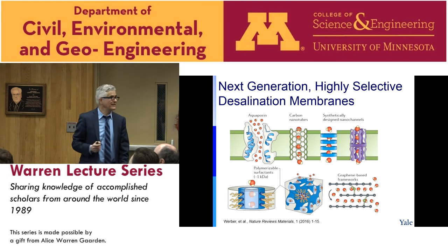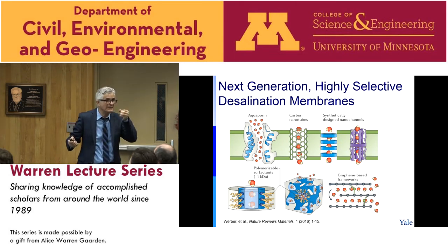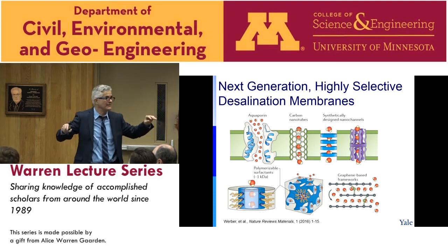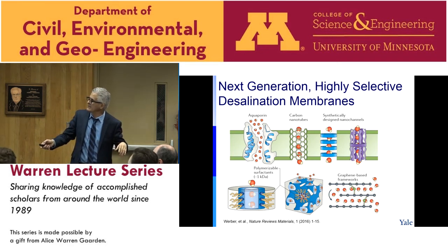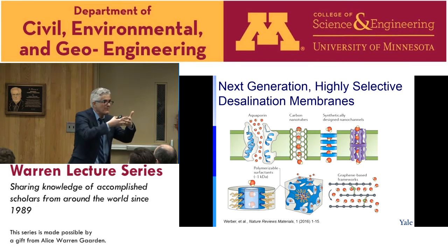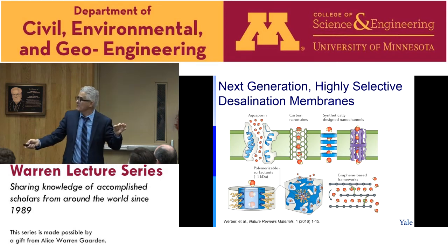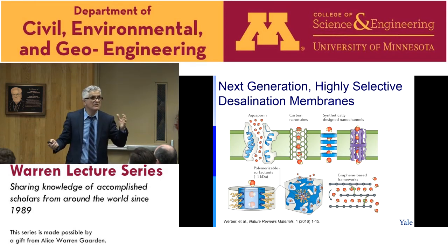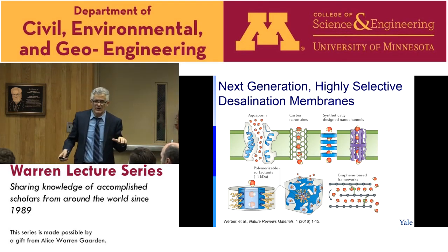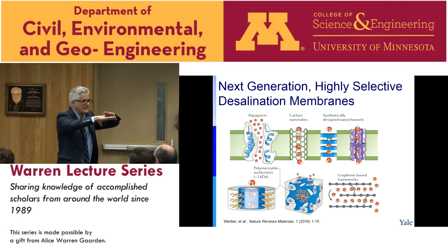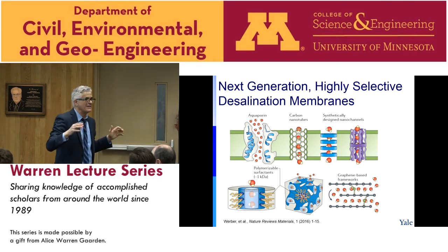We also discussed synthetically designed channels that you can design and incorporate in some impermeable matrix. Not easy, it's mostly by self-assembly. And we also discussed some small molecules like surfactants or liquid crystals that you can assemble with bottom-up approaches and create these pores in the 1 nanometer range, which can hopefully achieve desalination. So here we also discussed graphene oxide. People suggested graphene oxide, by putting these layers of graphene oxide, mostly because the Nobel laureate Geim suggested it.